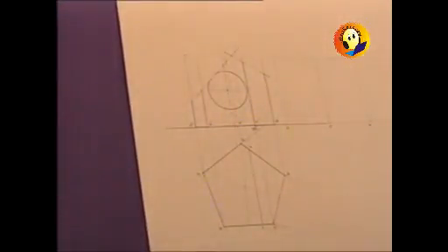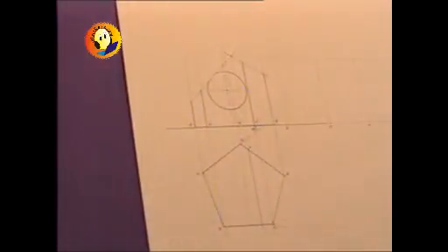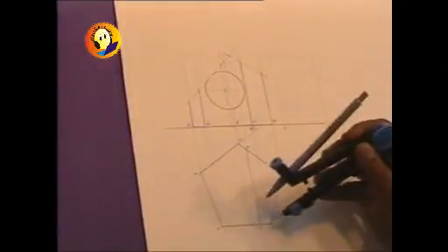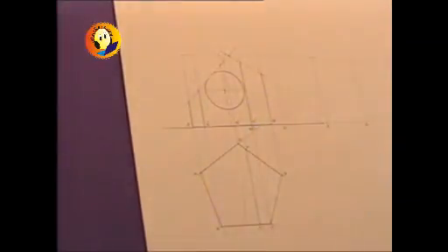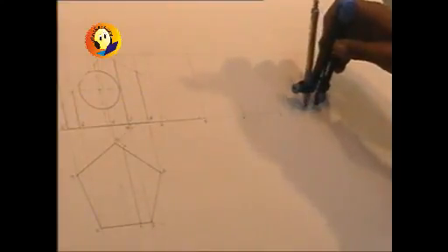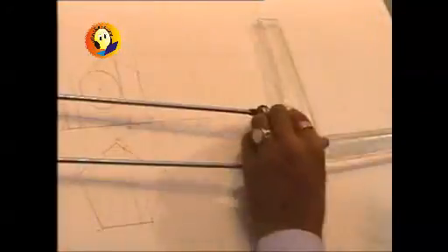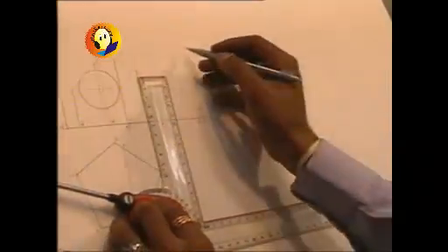Now to mark these 2 generators, we will have to take the distances in the compass, that is from D towards E, D2 distance, and should be marked on the development as from D towards E to get point 2, and from C towards B for point 1, and it can be shown on the development as from point C towards B. So we got point number 1, generator for 1 and 2, and now those generators can be marked. So these are the 2 points of the top which are present.